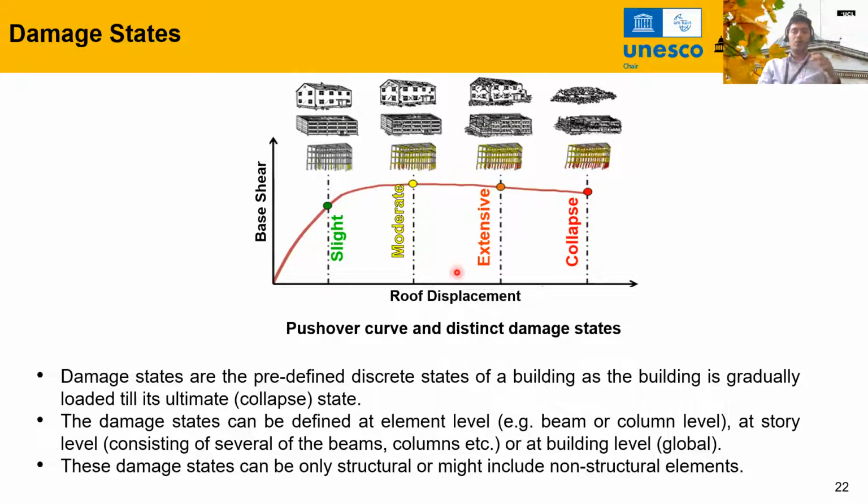Now, where is my slight damage? Let's say few elements, minor cracking, hairline cracking. So this is the slight damage where your elastic region ends. So you were in the elastic range up to this point, but now you are slowly moving into the nonlinear inelastic range.